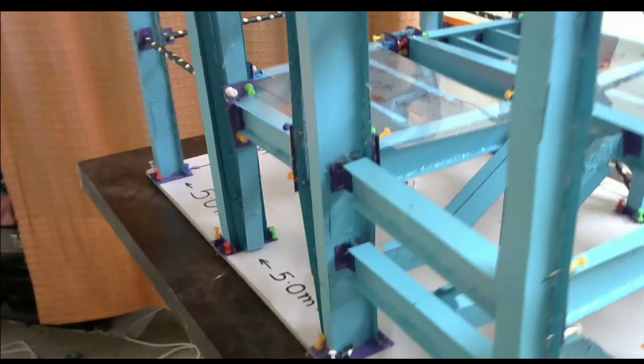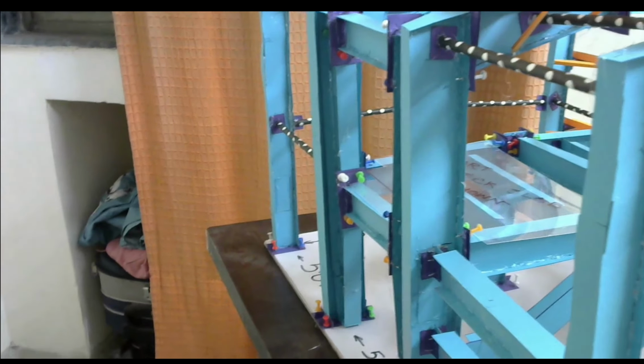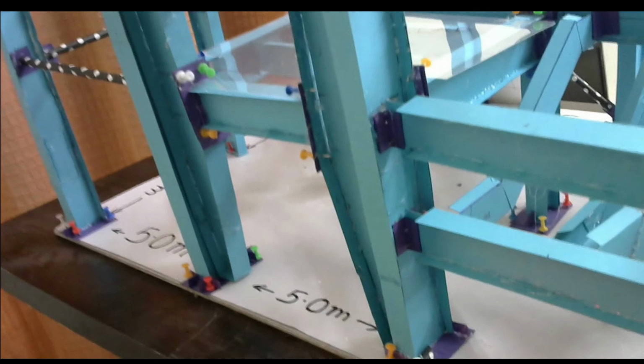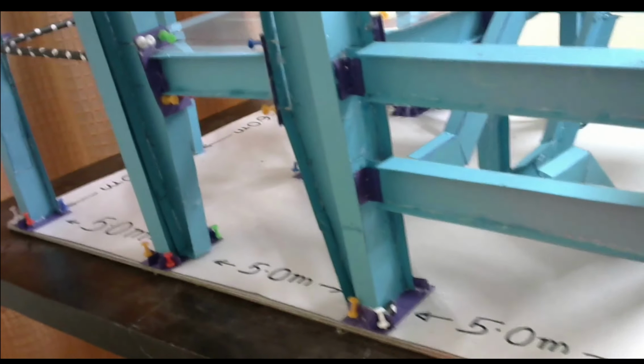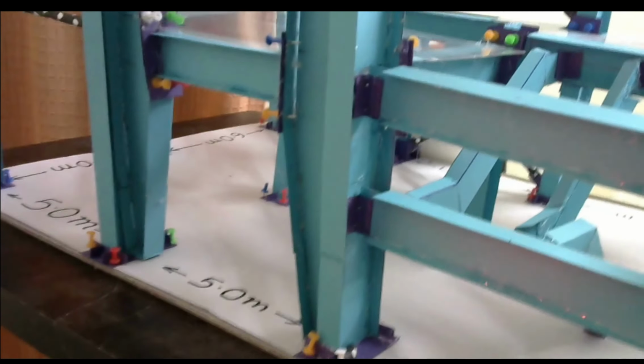You can see there is a portal frame. So obviously the forces will be transferred by flexural action, that is moment action, to this portal. The forces will be transferred to the foundation. So LY is restrained. So LY will be 1.5 meter for this column.